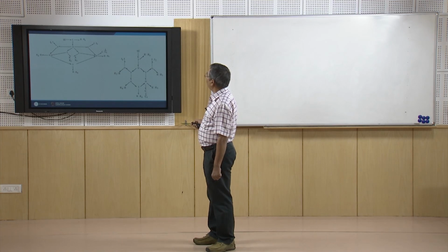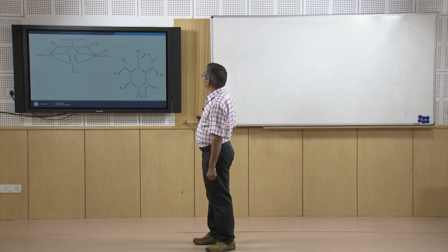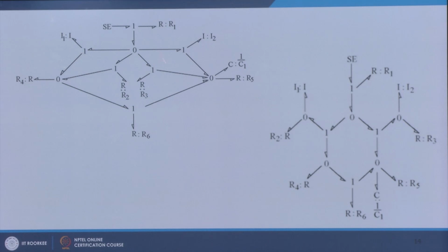Next, this bond graph can further be reduced as you can see here. So, we have SE, and then R1 is here, okay, and then this 0 junction is here, then this one, and here I have I and the other R2. In fact, I can first find out the voltage difference across these two, and then I can put I and R here. So, this is what I am doing.